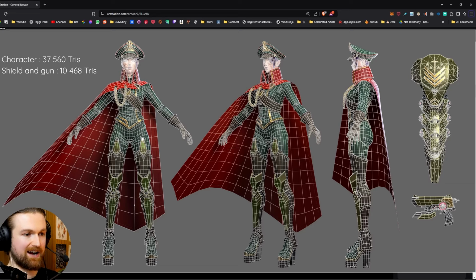So the way you've laid it out, I'm assuming that you want to be simulating this, and that's for a couple of reasons. First of all, I see that there's some texture on the cape itself. So when this is simulating, that texture line is going to maintain its visual because there's more geometry to work with. With fewer polys during a simulation, those might stretch because the vertices are going far away from each other. So that's something to bear in mind.